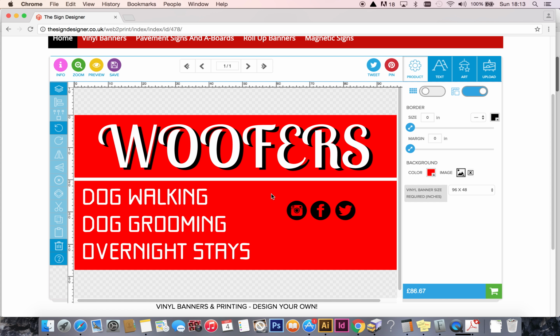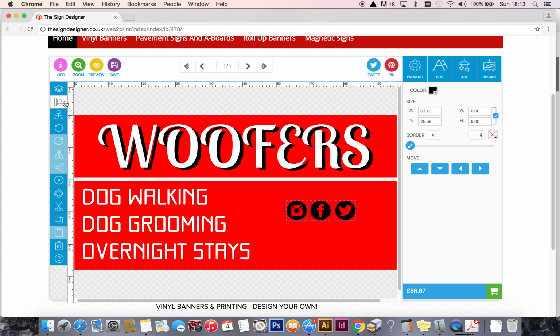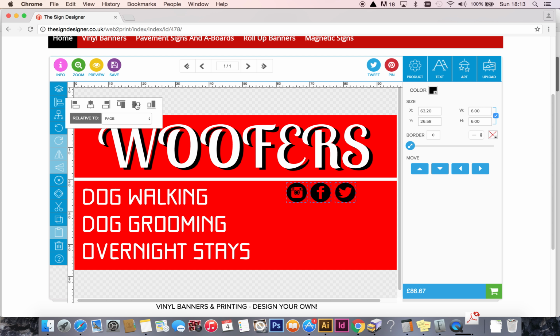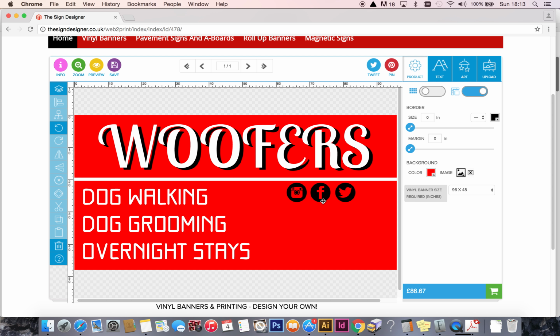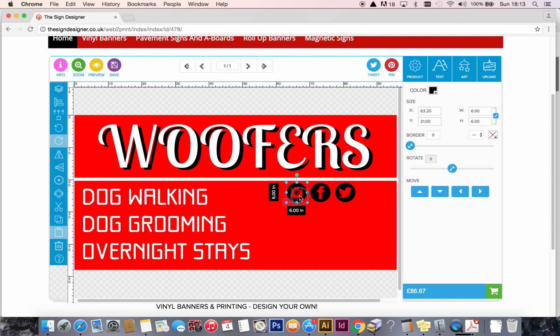So what I want to do is align them. So I'm going to rubber band, click, drag, and let go. And then with my align tool up here, I'm going to align them that way. That way. Okay. And I want them all to be white. Now the beauty of rubber banding, by the way, is when you rubber band, you don't need to entirely encompass the item. You only need to touch it with the rubber band and it becomes selected, like so. So let go.